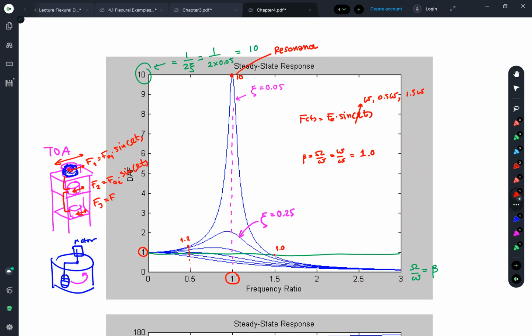But before I end up with the solution I recommend, another thing is, if I would like to avoid the resonance, assume this is under the resonance case. That's why the frame moves a lot, with very large displacement. Another possibility or solution is you have to change the mass of your steel frame, right?